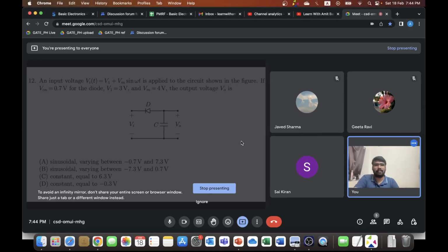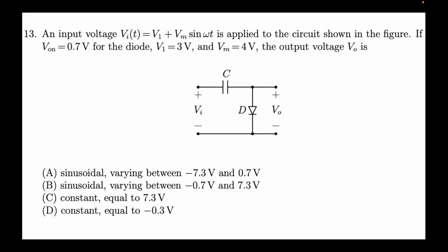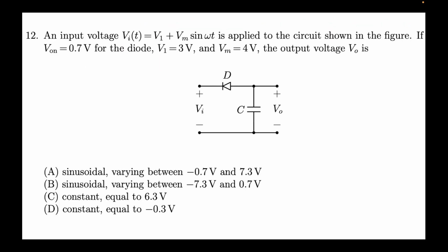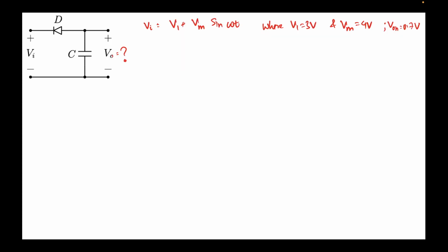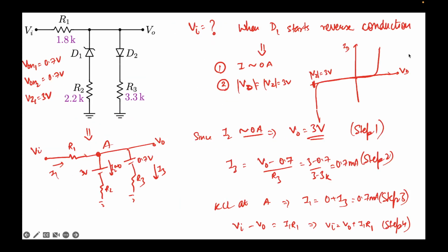Any doubts? So in forward bias, can't we use it as a voltage regulator, right? No, we cannot. I'll tell you. I understand why you're saying that. I can sense you're saying that qualitatively, this part of the curve and this part of the curve are the same, right? That's what you are arguing?